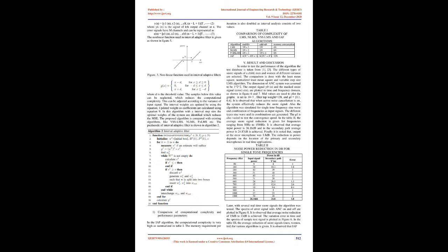In [18, 27], the drawback of the extended Kalman filter, applied to nonlinear GPS/IMU system with huge uncertainties, is resolved by using interval Kalman filter. In [28, 29], the calculations related to interval matrices, such as inverse of an interval matrix, symmetric interval matrix, eigenvalue bounds are discussed. The filtering method is proposed, which iteratively improves the approximation.